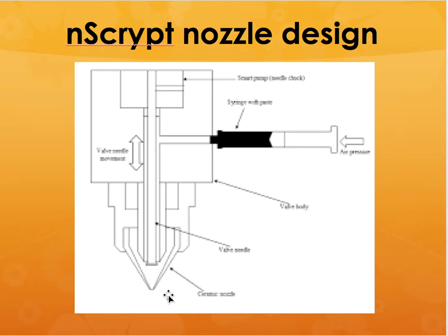So what is the advantage with having a highly loaded system? For example, typically solids loading in a binder system or a liquid system is of the order of 30%, because going above that increases the viscosity of these inks by multiple orders of magnitude. So it becomes extremely difficult for these materials to be delivered.